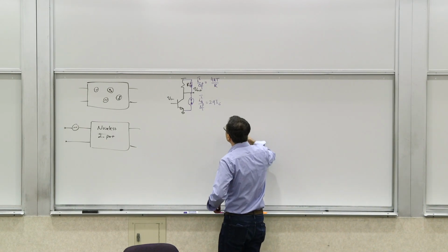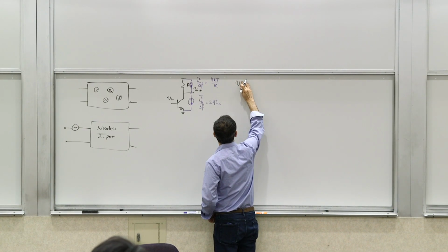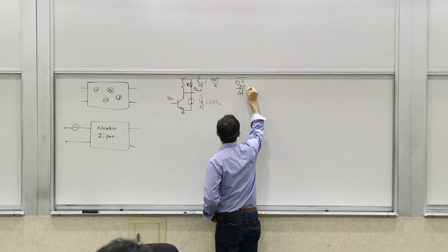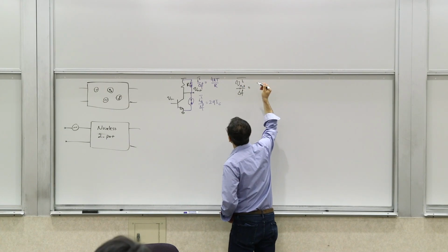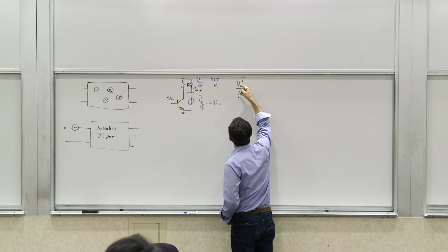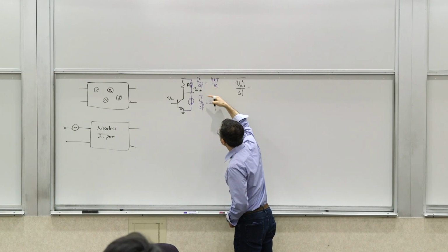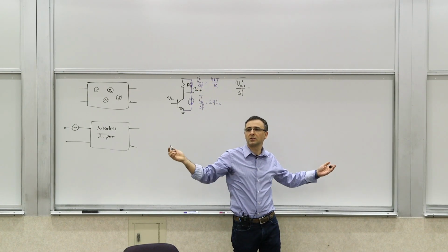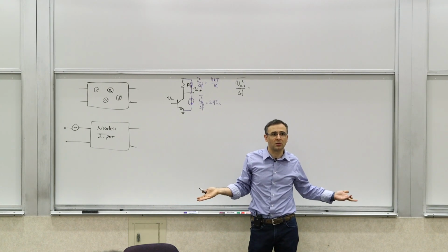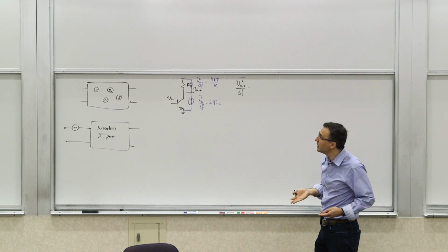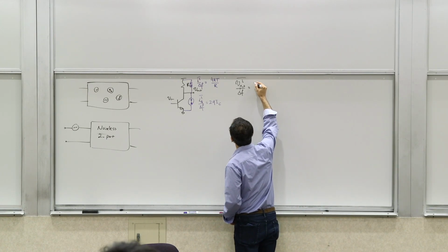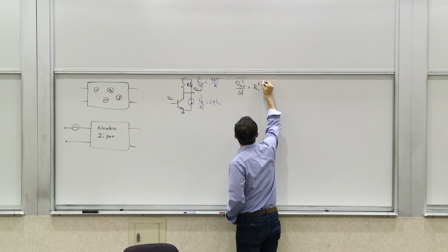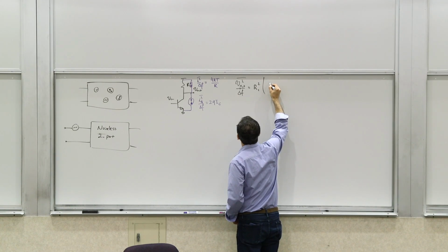So what is the total noise at the output? If I say Vno squared, V noise at the output squared, this is the noise power spectral density. So basically, it would be the sum of, and these two noise sources are uncorrelated, right? Because they're generated by two different mechanisms in two different devices. There's no reason for them to be correlated. So you have to add them in power. You add the power of these noise sources. So basically, and then multiply it by R1 squared to produce the output voltage power.